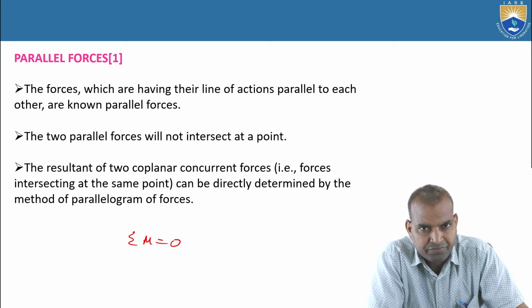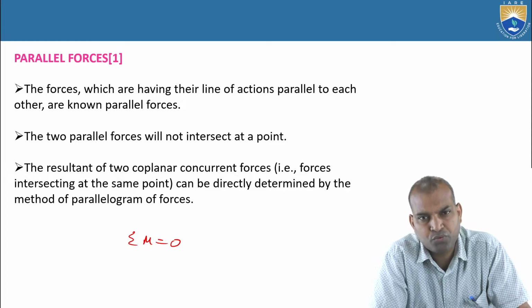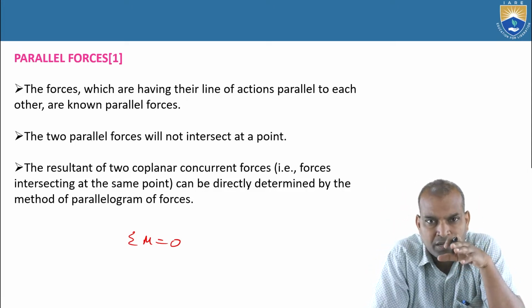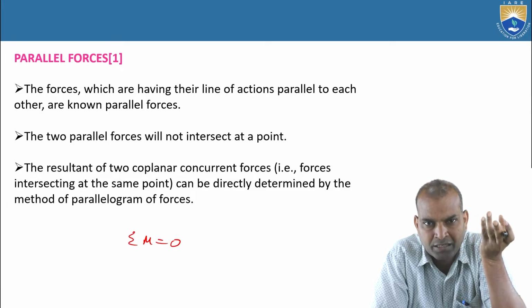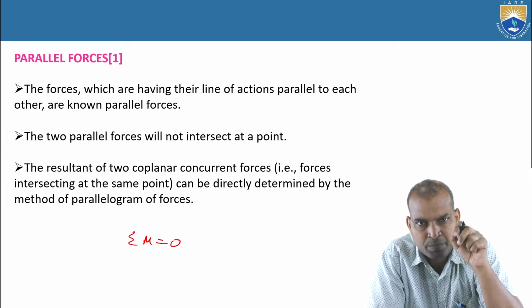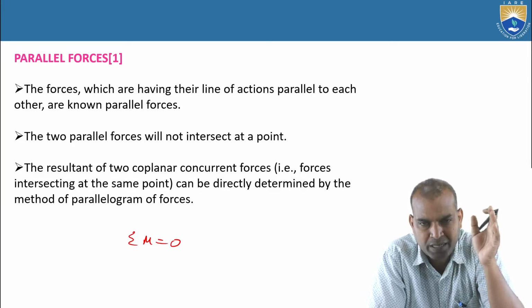Here we are going to study the resultant. If you want to find the resultant of such a coplanar parallel force system, we can't apply the law of parallelogram of forces. Yes, we can apply the resolution of the force to make it parallel.